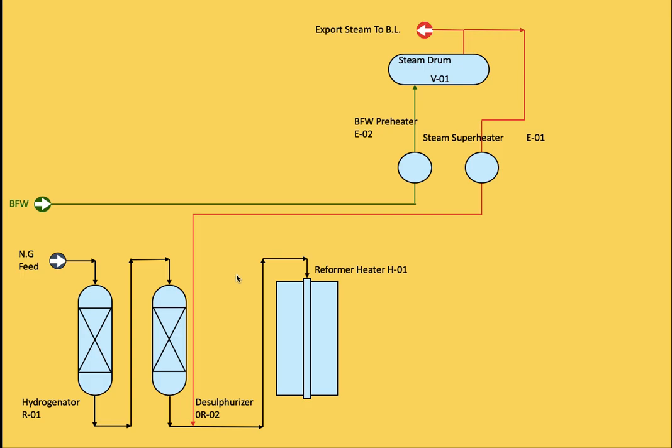And I need to discuss the reformer here in detail and add some new knowledge related to the reformer. A hydrogen reformer is not a single reactor, but a complete reforming process unit, whose main reactor is a tubular catalytic reactor, fired from the top. The main function is to convert the hydrocarbon, mainly natural gas or lighter hydrocarbon components, with steam into hydrogen-rich gas or synthesis gas.